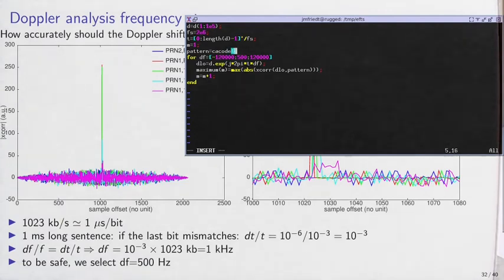I know that in this data set, space vehicle number 18 exists, and this will be at a data rate of sampling frequency divided by 1.023e6, because I know that it's transmitting at 1.023 megabit per second. So for the pattern, we must make sure to subtract the mean value from the pattern. And once we've done this, we have the whole acquisition sequence of a GPS data.